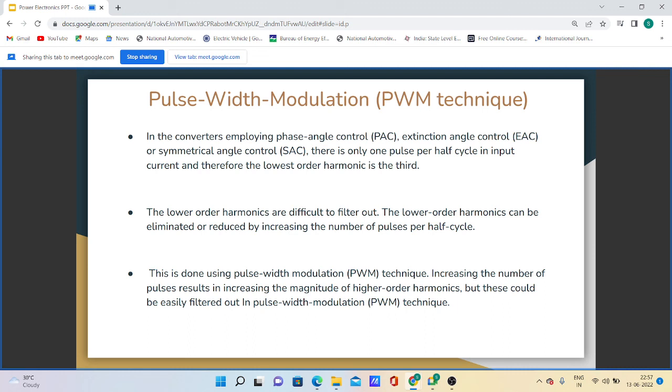Pulse width modulation is a technique that generates variable width pulses to represent the amplitude of an analog input signal. The output switching transistor is on for more of the time for a high amplitude signal and on for less of the time for a low amplitude signal.